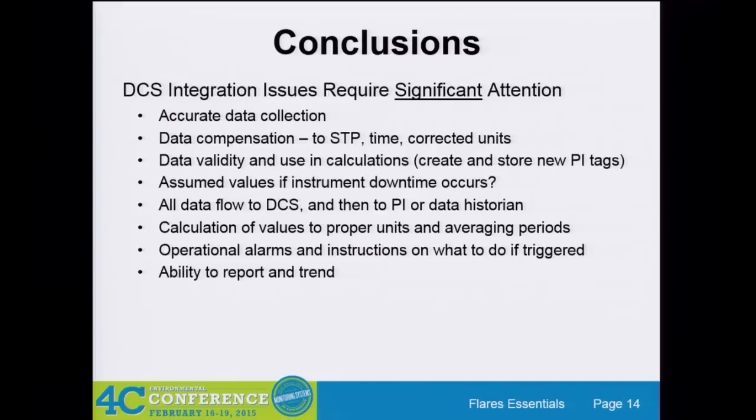One other thing I forgot to mention was, when you think about those temperature and pressure probes, if you're in an enforcement type situation and you could get stipulated penalties from these meters, a lot of folks have started to put a sense of redundancy in their system. They don't ever want to get stipulated penalties because they didn't have a pressure probe. So basically they've gone to installing 3 pressure probes and 3 temperature probes on their flare header.